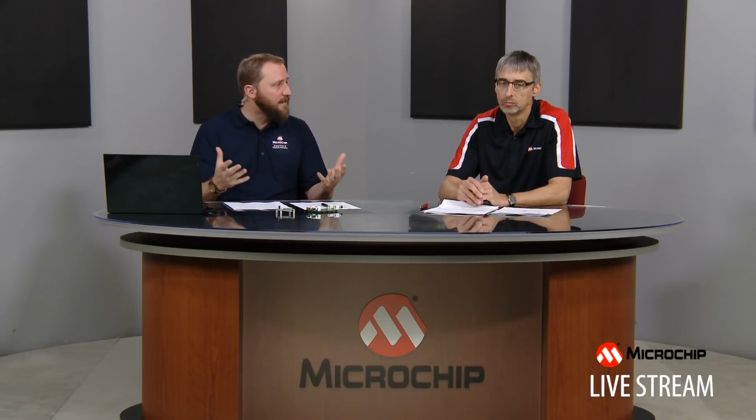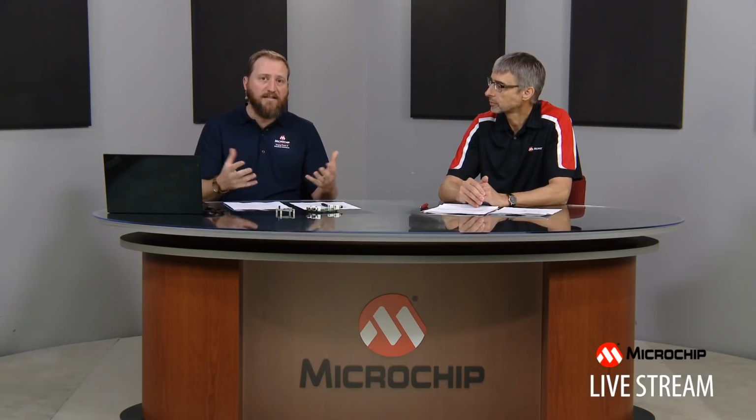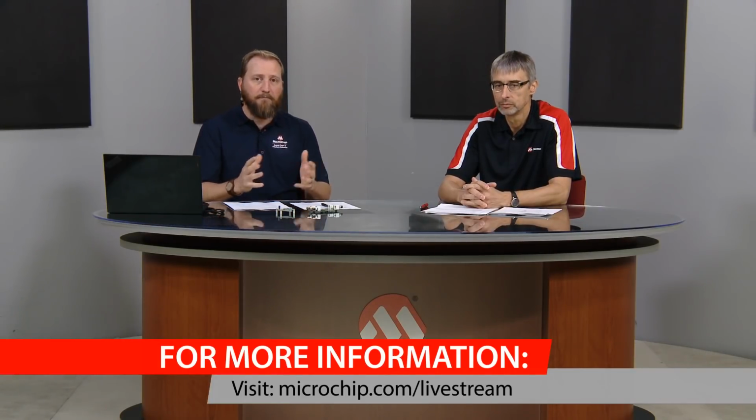And if you're flexible on the bandwidth that you require in your system, then maybe you find one that fits the power budget rather than the bandwidth requirement. Right, we do see some great applications for these zero drift amplifiers in battery powered applications with new process technologies, new and improved design considerations. These devices are becoming lower and lower in terms of their supply current. So they are still relevant for battery powered applications, but as Stefan mentioned, you need to be concerned about selecting the right amplifier that would fit your power budget and still satisfy your other performance needs.